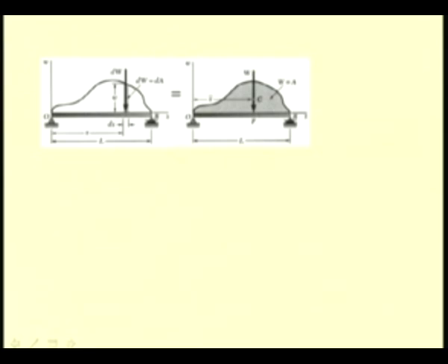In order to determine that, we can sum the moments of these individual incremental forces about, say, a point O, and equate it to the moment of this concentrated load about the same point O. By doing this, we can determine the moment arm for this concentrated load W.